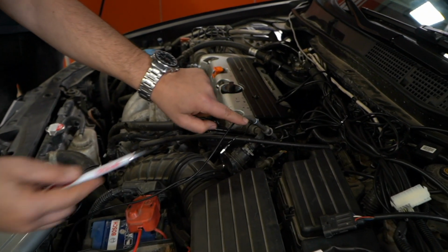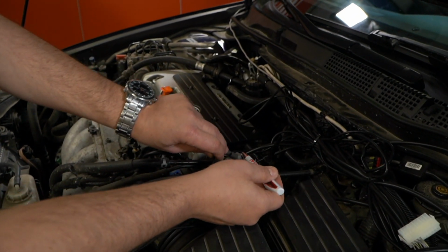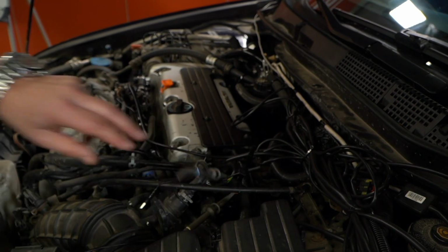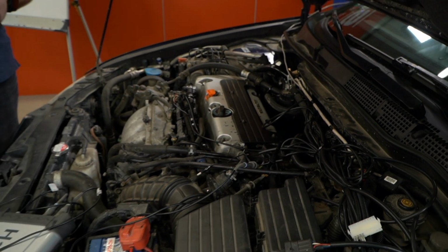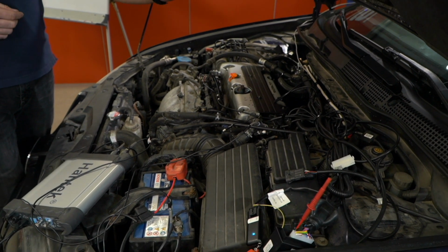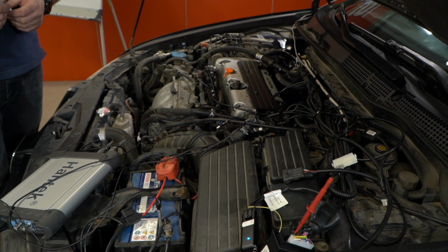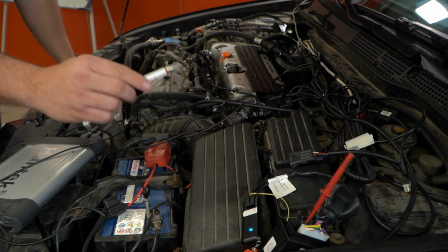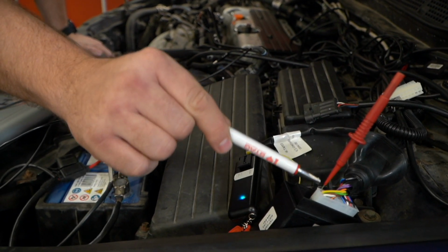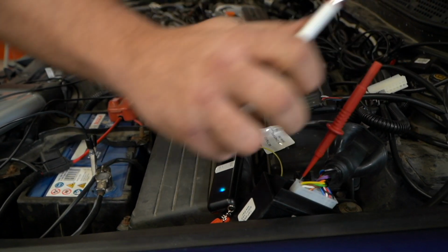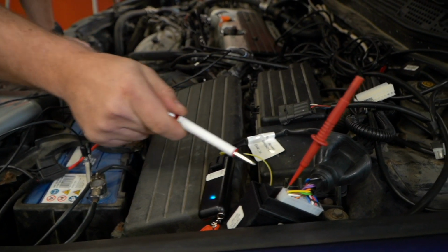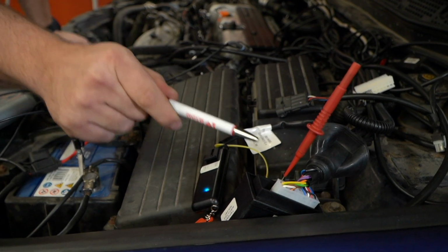The blue probe is connected to the camshaft position sensor on the left, and the yellow to the one on the right. The crankshaft sensor in this engine is located at the rear end, and we have very tough access to it. That's why we have the probe connected directly to the TAP socket, and we'll read the crankshaft signals later directly from the TAP unit.